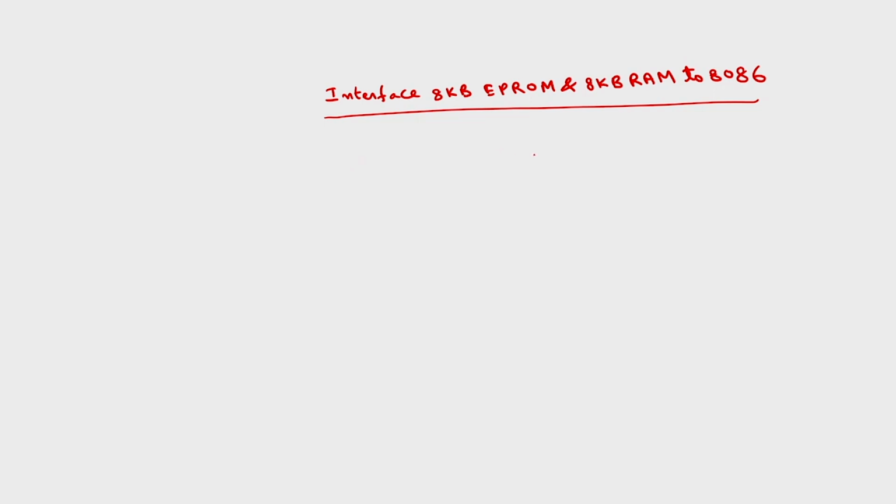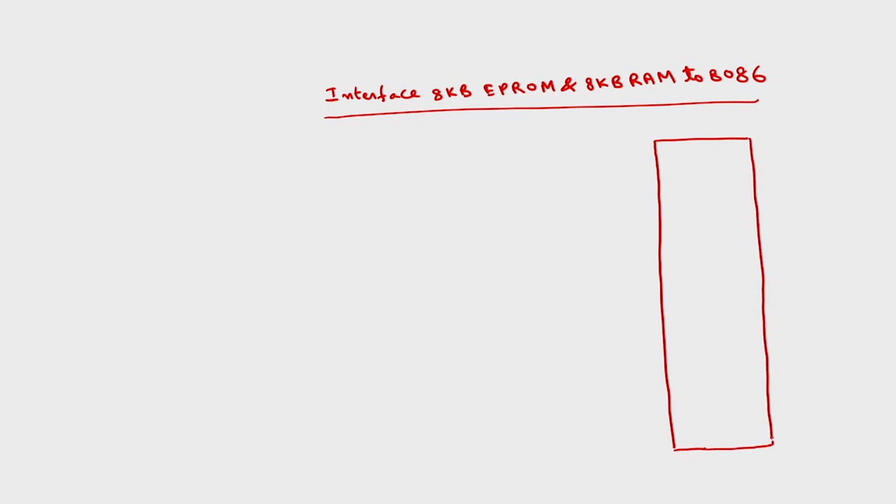We assumed that out of this 1 megabyte, I want to interface this EPROM in the last 8 kilobytes of locations. So the ending address will be FFFFFH.